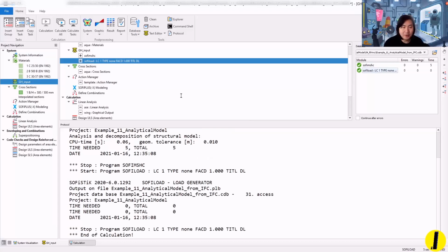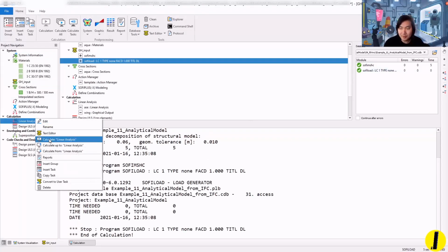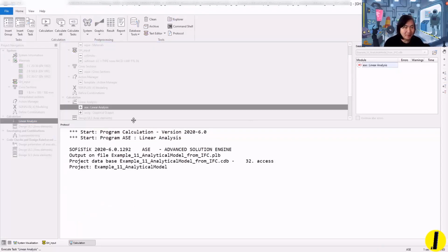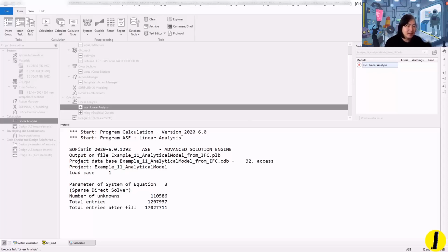It is complex workflow, but still it will save a lot of time to redraw the Revit elements with native Revit elements. So we can just open new Revit project file and link IFC, and then this script should work completely normal.